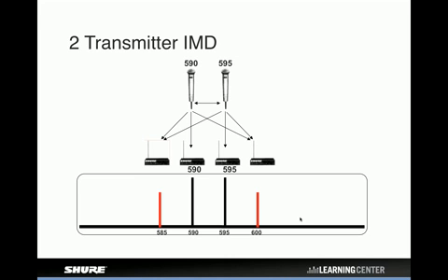And there could even be more products than that. These are just what are called the third order intermodulation products, and they're typically the strongest. There could be fifth order, seventh order, ninth order. Depending on the system we're looking at, maybe you have to consider those, but on most higher end systems, you don't. But at any rate, that's the third order intermod products.